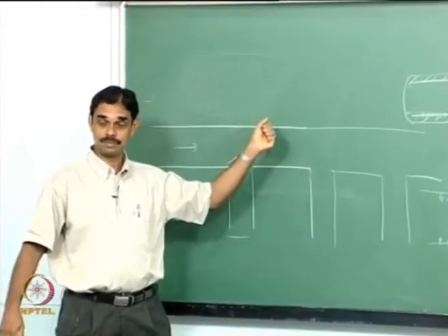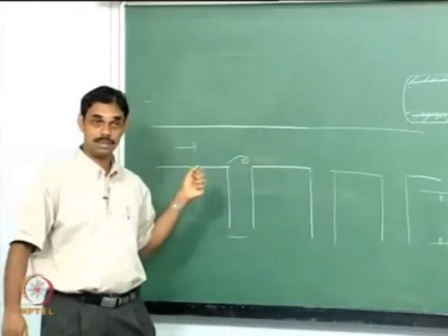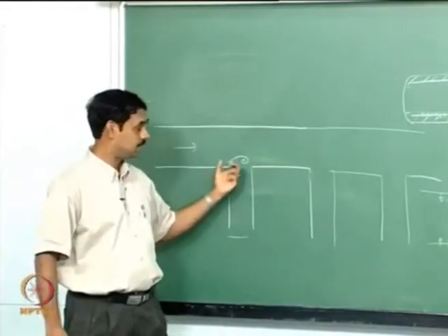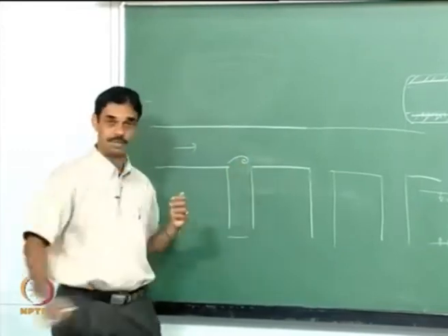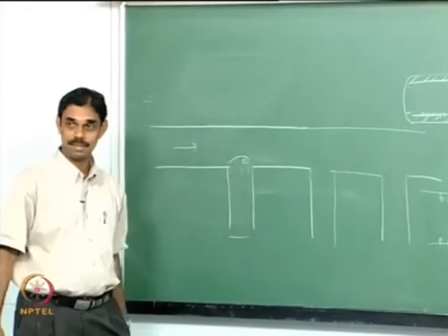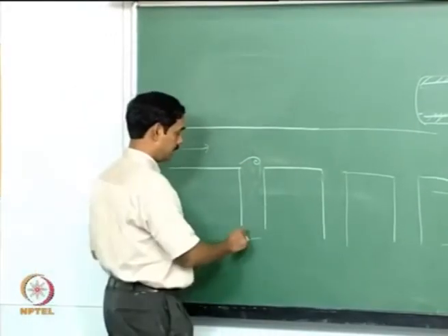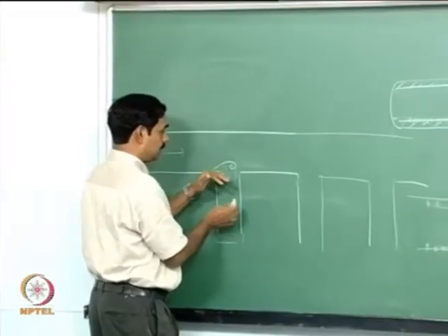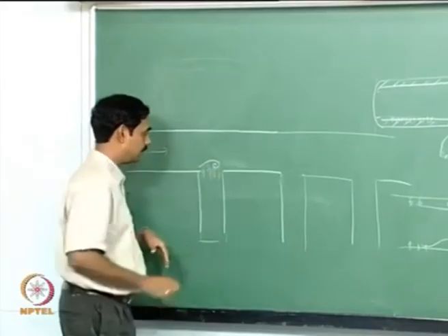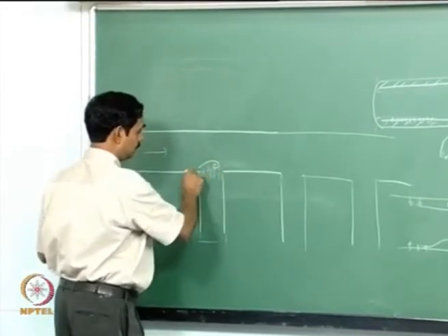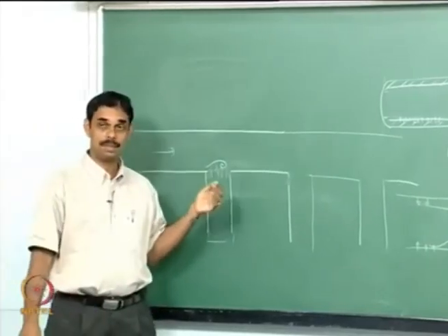So when you have natural gas being distributed this way, anytime you close this branch, if there is a flow, then I think this will not be a problem, because the vortex will be disrupted. But if not, you will have a resonator here and the vortex is crossing the lines of acoustic streamlines, and you have large amplitude oscillations, and then you can cause a lot of damage to the pipes.